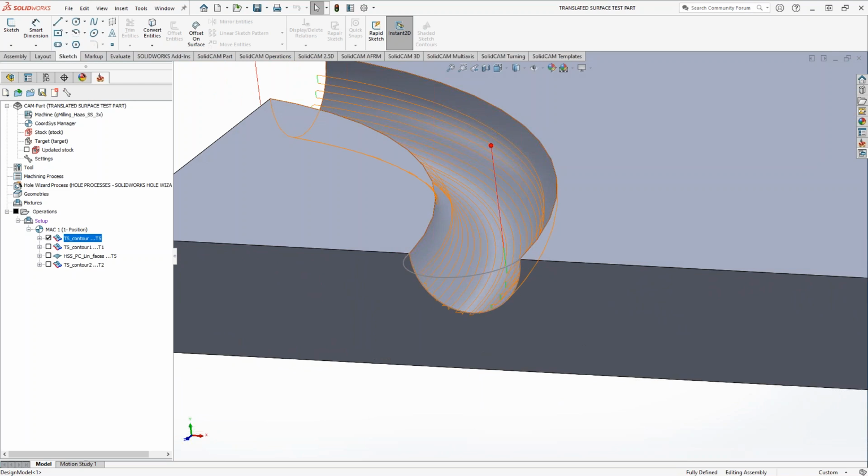And honestly, this could be a really great toolpath to use if you didn't have HSS. Because with HSS, linear, constant Z, you can pretty much achieve the same motion here. With full HSS, you definitely can replace this with some better toolpaths. But if you only had the 2.5D package, the basic Express package, this is a great way to do this sort of feature here. And that's just the finishing portion of it.